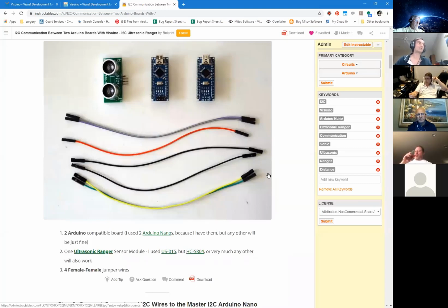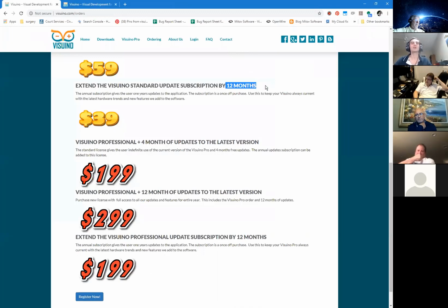So you're saying to use two boards, one to process the communications and one to execute the actions. Correct. You can use I2C communication. That's very clever. Yeah, thank you. It's often used. So you have two options. You can use I2C communication between them, or alternatively, you can just use COM ports and have one of them talking to the other over the COM port with the packet and unpacket and everything. So you have plenty of options, right? So that would be one way.